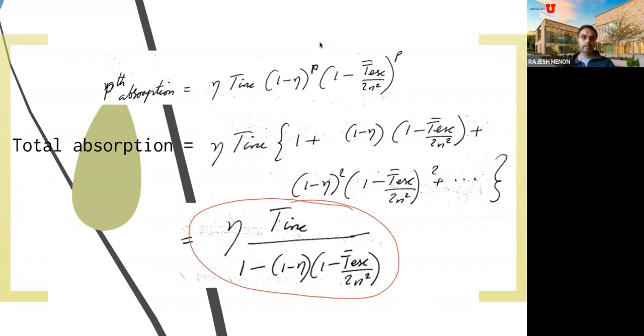A couple of interesting things, of course. Again, our design goal here is to maximize absorption. So of course, how do we maximize this? You want to make sure that the transmission into the PMMA, this is the T incident, is as high as possible. The absorption at each event when it hits the PMMA silicon interface is also high. And the rest of the stuff is straightforward.